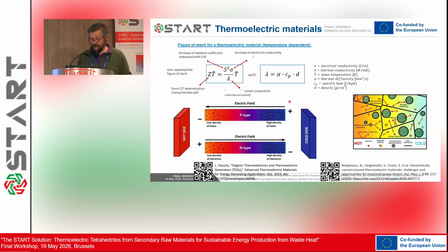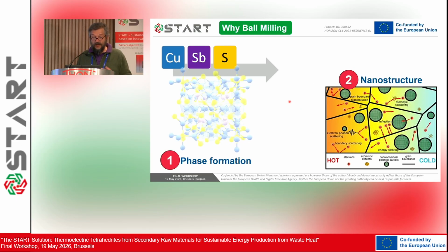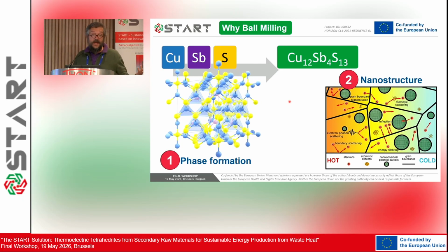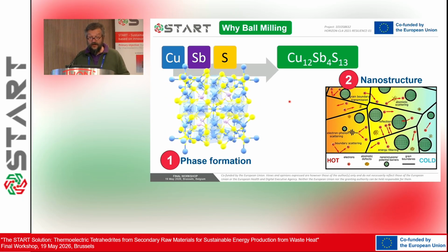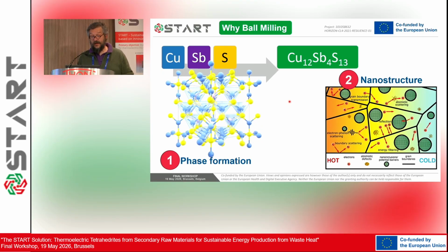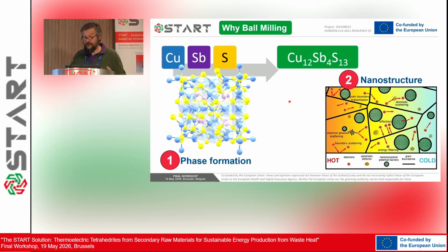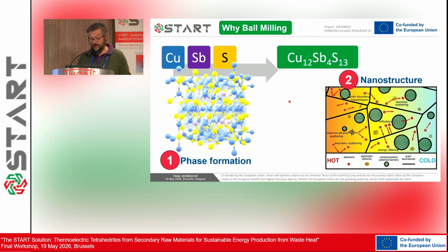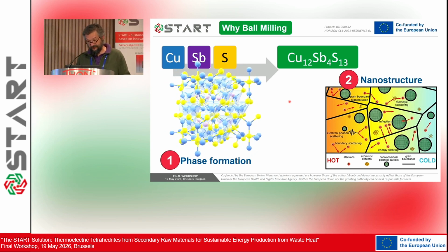But yeah, this is the second reason why we choose the ball milling, to have a direct formation from the elements and also the nanostructure. Combining these two, we can aim to have these thermoelectric materials from tetrahedrites.